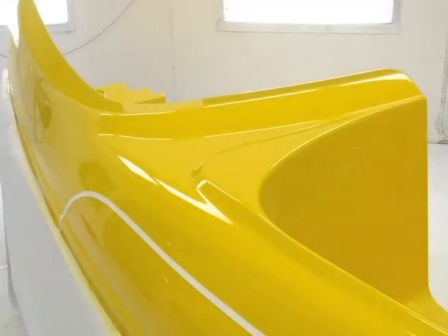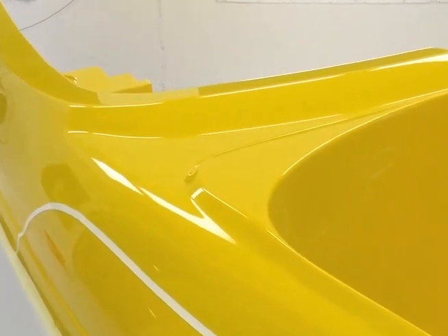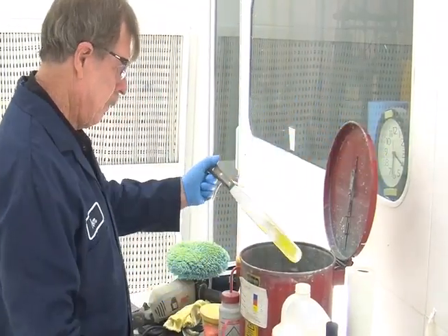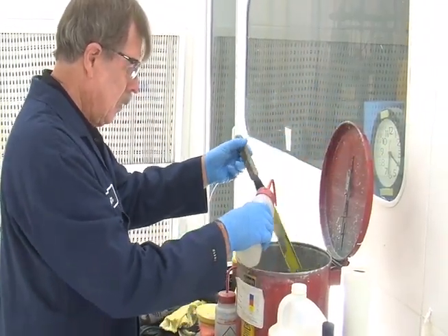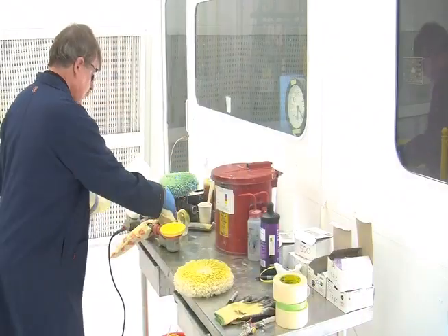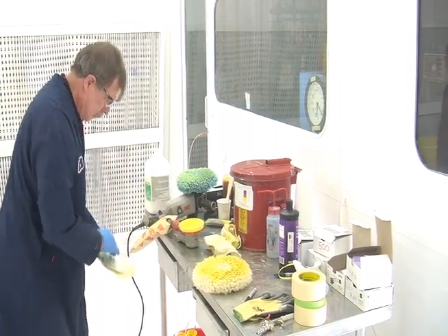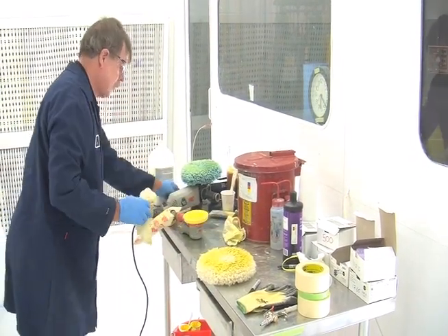If the patch colour does not match the part colour, verify that the same batch of gel coat was used. It may be necessary to spray patch over the spot patch. Sometimes it is necessary to patch an entire section at one time using edges or corners as boundaries for hard to match situations. During and after the patching process, make sure that you clean any equipment used. Also make sure to store and dispose of materials and supplies properly. Always read the MSDS before using any chemicals.